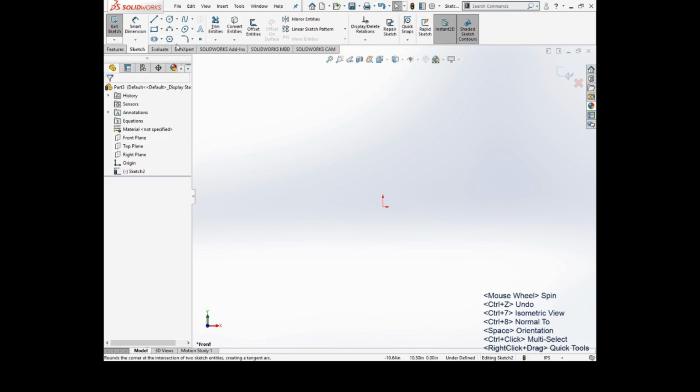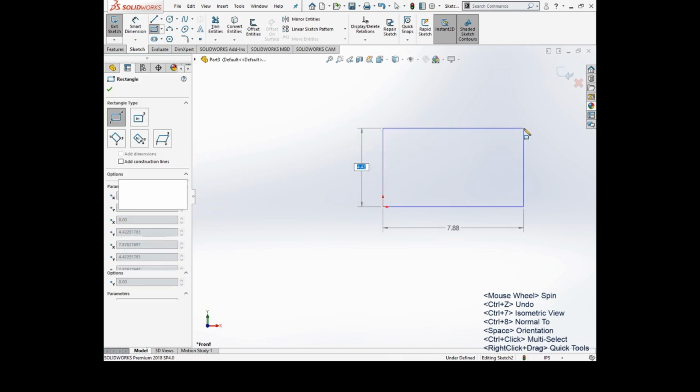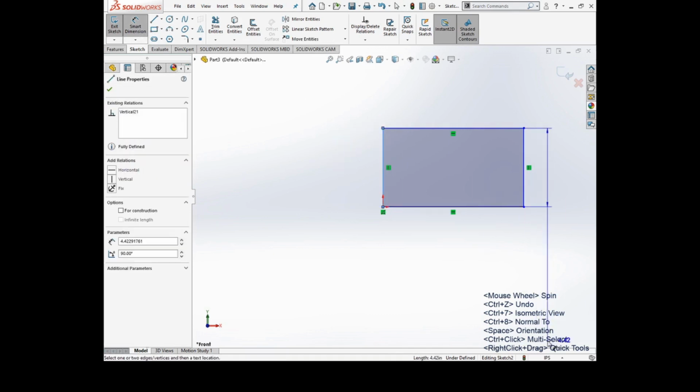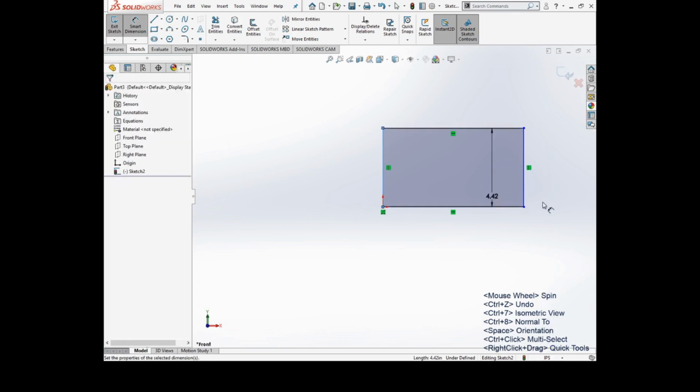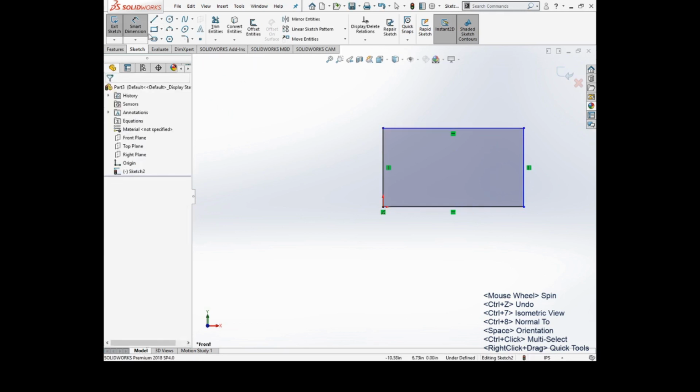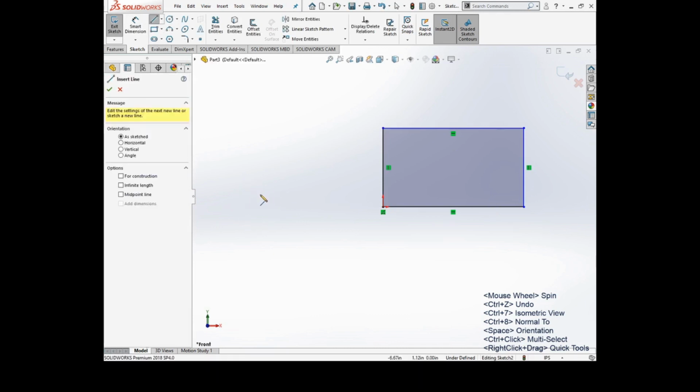And then, okay, so we'll get to fillets next. Whoops. All right, so if we grab a rectangle and pop it in, let's go over dimensions first. Let's grab the Smart Dimension tool. Currently I have inches. You can go inches, millimeters, centimeters, or meters. Another thing that's useful, if you right click and drag, you will see these four different options. You get line, smart dimension, circle, and rectangle.